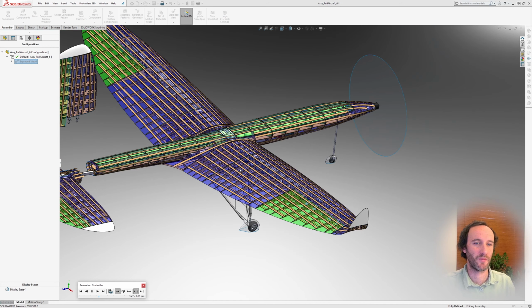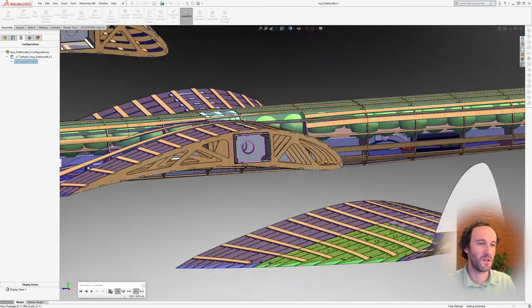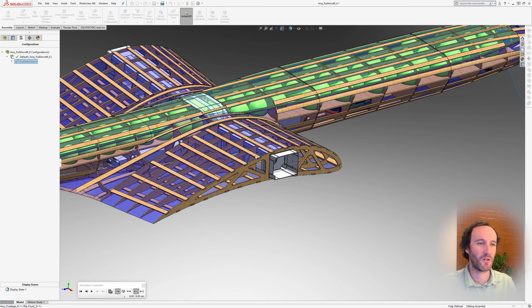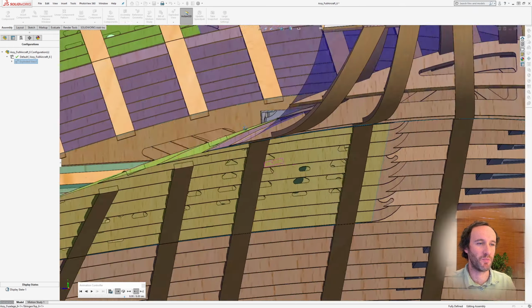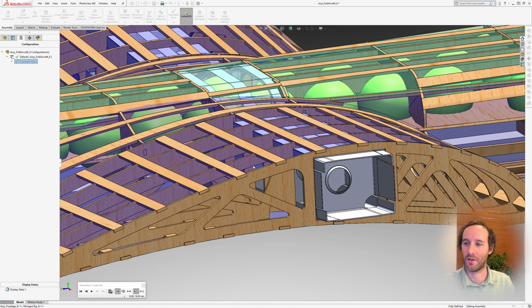So this is what it looks like inside the wing box here. Now the stringers are pretty frequently 1/2 inch by 1/8 inch balsa wood strips, and the skin could be a vacuum formed plastic or a shrink formed plastic coating draped over, that adheres to the stringers and the ribs. But the techniques that we'll learn to design these rectangular cross-section stringers are intuitive to expand to the general case of other types of cross-sections.